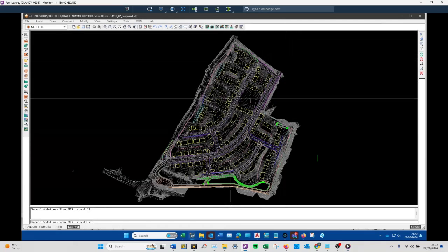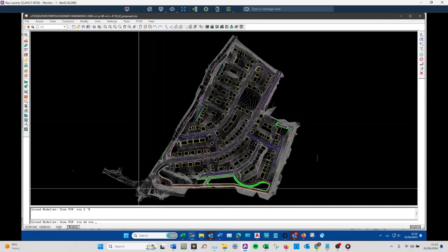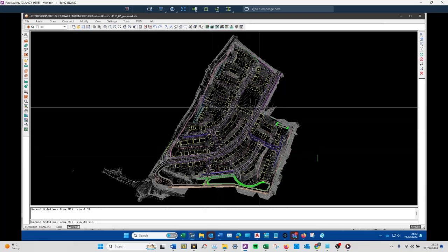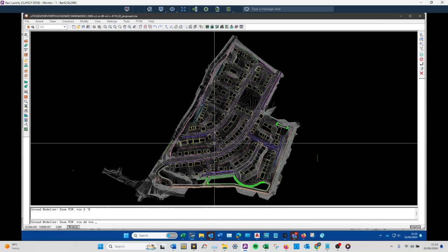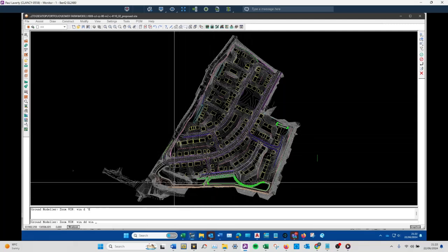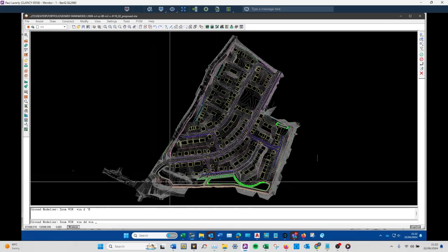At the entrance we have a new roundabout that leads to the main spine road running through the site. There's about 10 secondary roads and about 8 stub roads and turning heads. To the south we have a couple of attenuation basins with their own maintenance roads, and a pumping station with a couple of access roads and some footpaths, which I've done as roads as well.